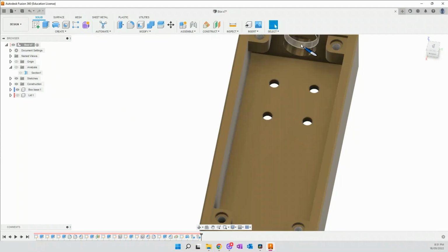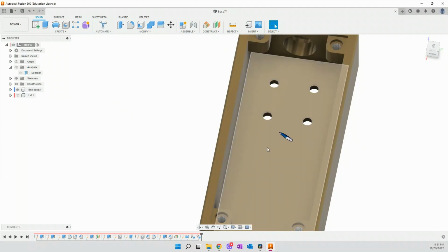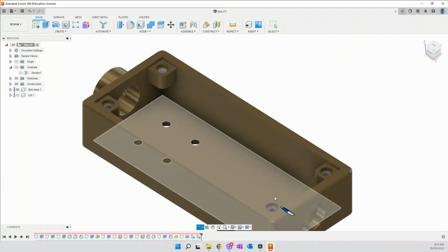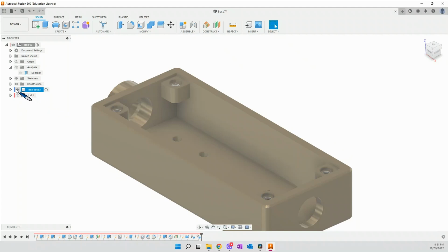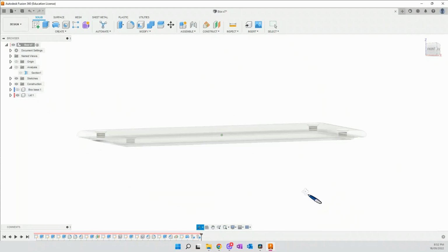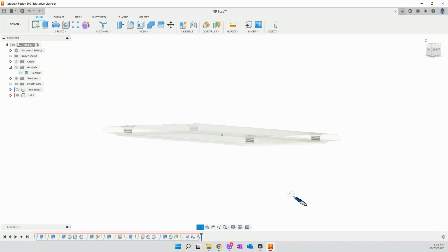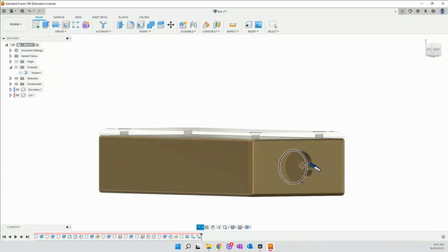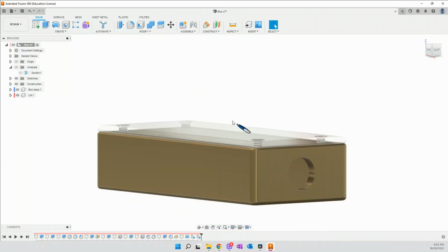And in the example I'm showing you here, we've used extrudes, cuts, holes, revolves, offset planes, fillets, chamfers, all the common things you're going to need from your day-to-day designing. Once we've done that, we'll create a lid that will fit and show you how dynamically all of the parts can change with a simple measurement change.